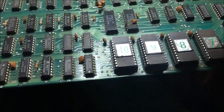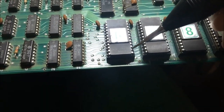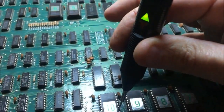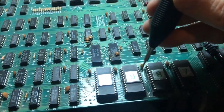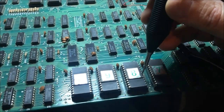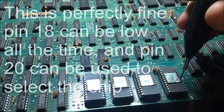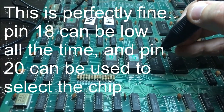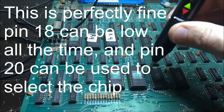Pin 18 is the enable on these 2732s. 13, 14, 15, 16, 17, 18. It is enabled low, but this is not right. All of these, the enable pin on every one of them is low. That's not right. 18 on these, 13, 14, 15, 16, 17, 18. This is the enable pin on these.